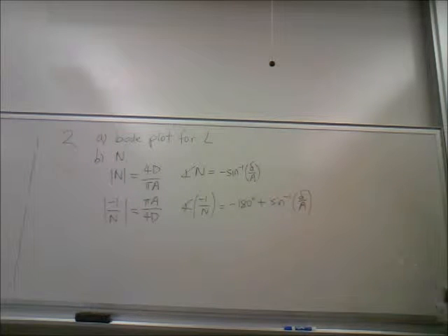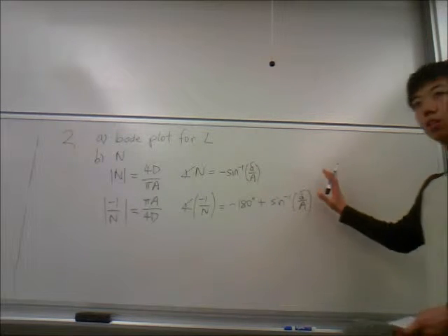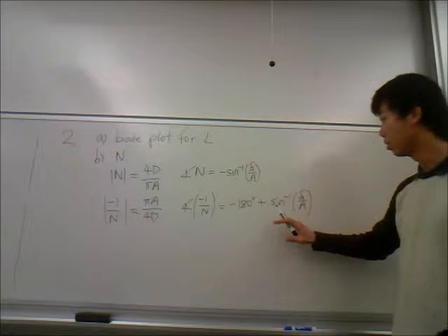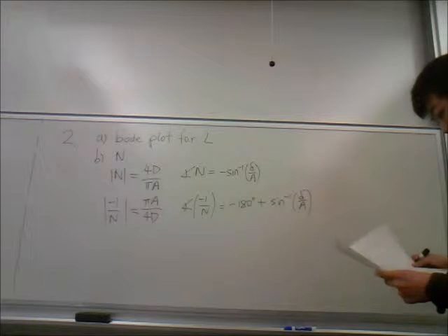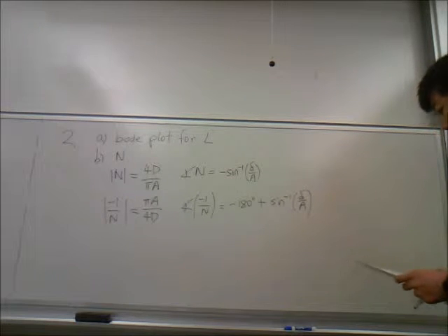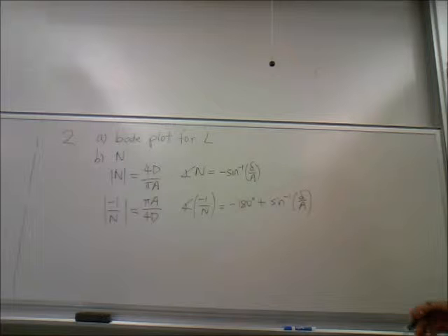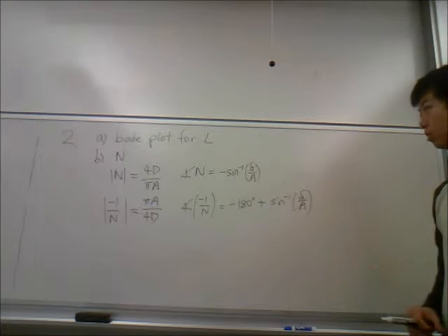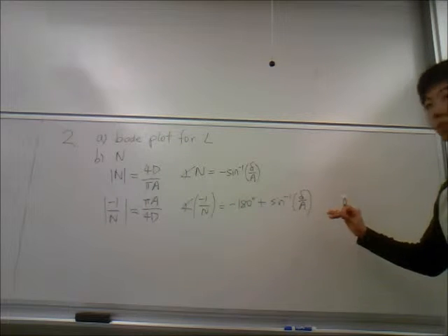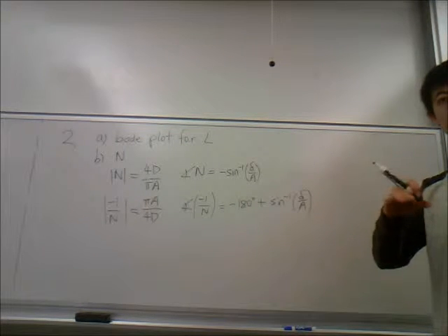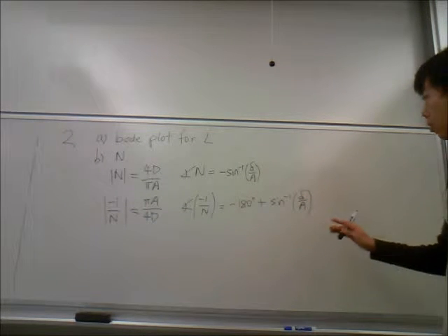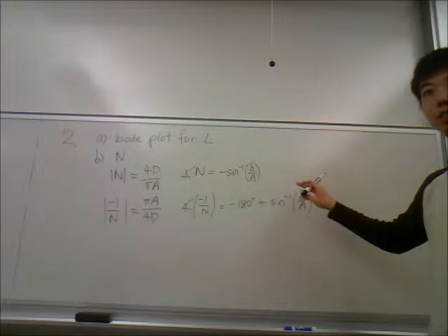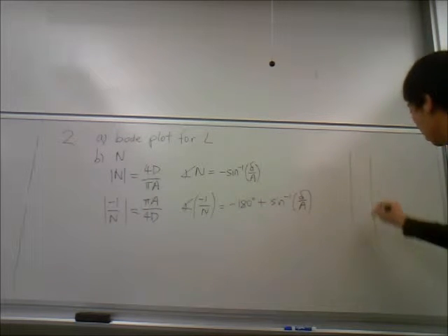So for the first part, pretty straightforward. Draw the Nichols chart, and then find the intersection. Then you'll be able to find omega and A of the limit cycle. Then it asks, what range of K? I think there's a gain K. What range of K will there not be a limit cycle? From the Nichols chart, you'll see that it goes something like this.